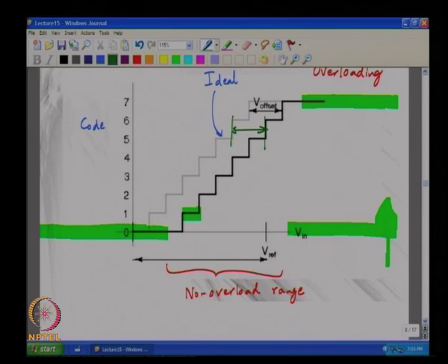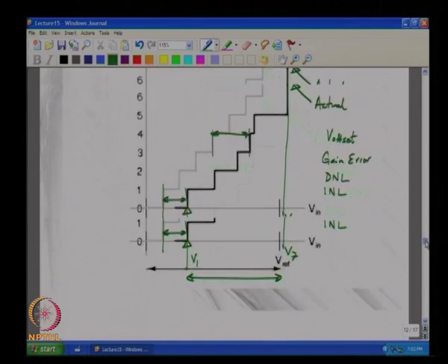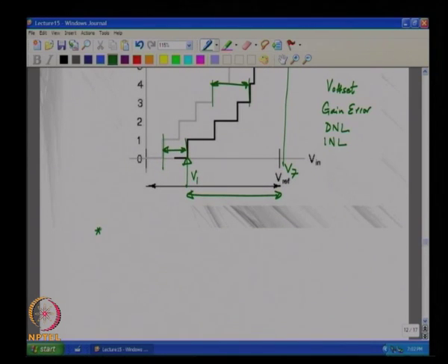So the INL is constant, but this is potentially a large number of LSBs, though otherwise my staircase is quite nice, with uniform step size and gain of 1. So it is not enough to remove the gain error; you must also remove the offset. To find DNL and INL from measurements, the first step is to remove gain and offset errors.